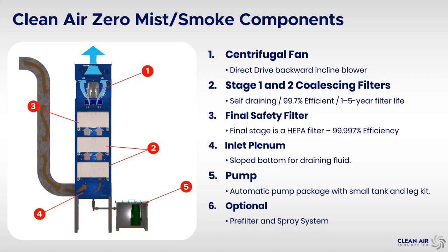But anything that gets through filter one, the first stage, stage two will filtrate anything from 1 micron down at about 99.7%, which pretty much gets everything. If there is anything that does get through, then we do have a HEPA sitting on the top, and that is a 99.997% efficient filter.